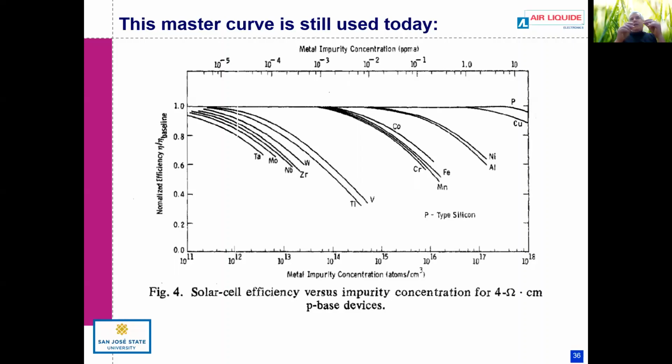If the conductivity disappears instantly as the light goes off, then you know that it's impure. But if there's conductivity for a couple of milliseconds after you turn the light off, then you know you've got pure silicon. That's a phenomenological way of assessing the purity of silicon, the suitability of that silicon for photovoltaic devices.